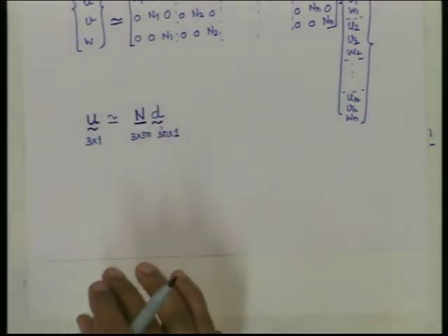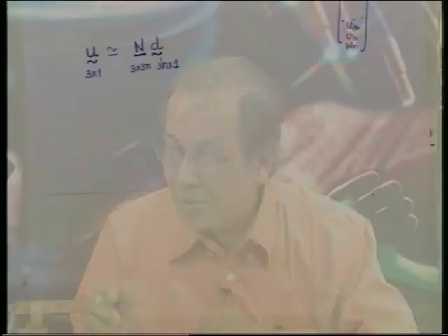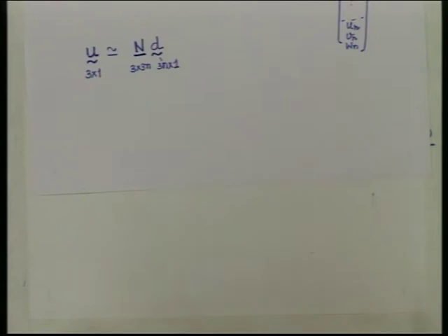We established that it was 1 minus x by L and x by L, N1 and N2, because it was only 2-noded. So the shape functions of the 2-noded linear element were 1 minus x by L and x by L. It is a very simple thing; it only looks complicated and tedious, but it is not, you just learn. So, having established the displacement, the next part is always